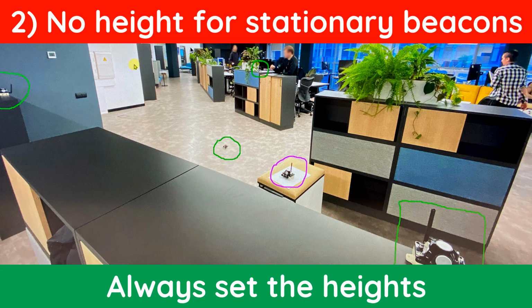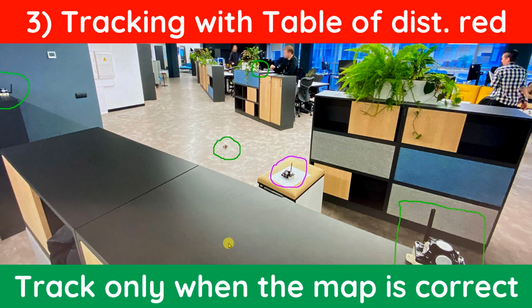If it's not, then the height is 0. And of course height is not 0 for this particular configuration, because this is on, whatever, 1.2 meters, 1.2 meters, 0, 1.2 meters. So the geometry couldn't even theoretically be built because the heights were different. But the system assumed that the height is the same. So major error. But line of sight is even more. Always set the heights for the stationary beacons.